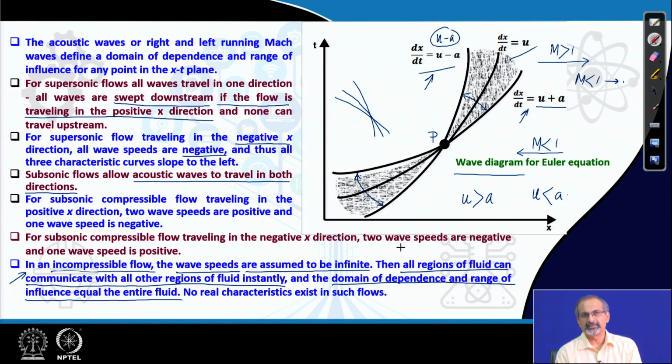So, you can imagine that from this wave diagram, it becomes clear to you that when you are solving Euler equations in a numerical sense, you have to take extreme care about how these characteristic waves are going to propagate through the domain. And we are discussing the problem only from a one dimensional perspective. So, you can also have multi-dimensional problems where the other directions x, y and z can also be coming into the picture.